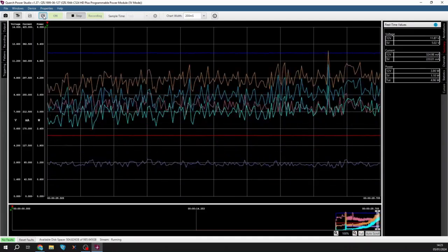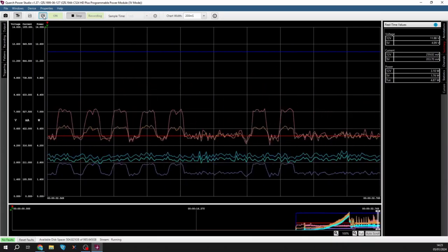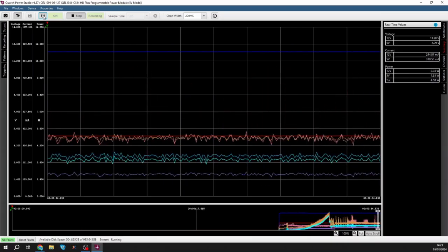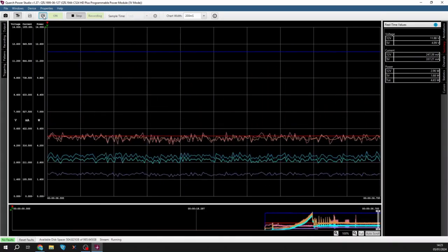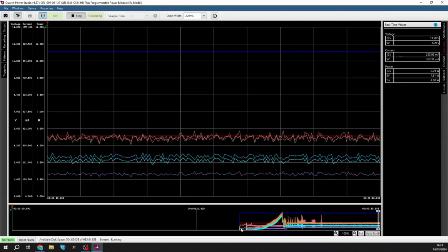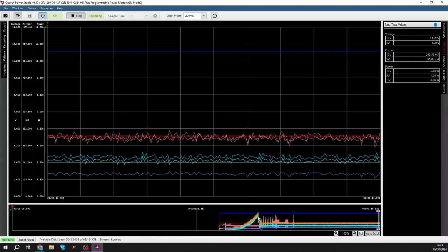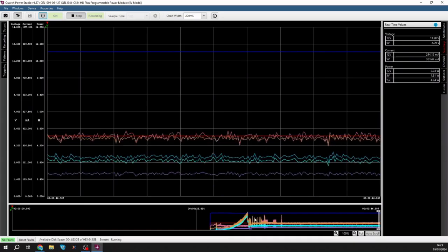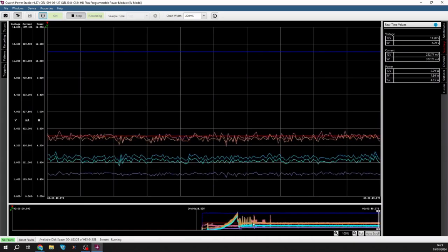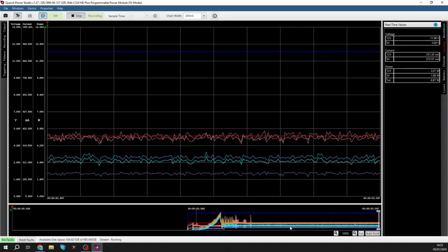Now, in the top window, we see the latest data coming in, and on the bottom, the timeline window, we see the longer term view of the trace and what's happened. You can see that the voltages, the blue and red line, jumped up immediately when I pressed on. Then we can see the current and power steadily ramped up as the motor began to run. And then we've got spikes here showing probably the head movement of the drive. Finally, we settle into a fairly stable state.